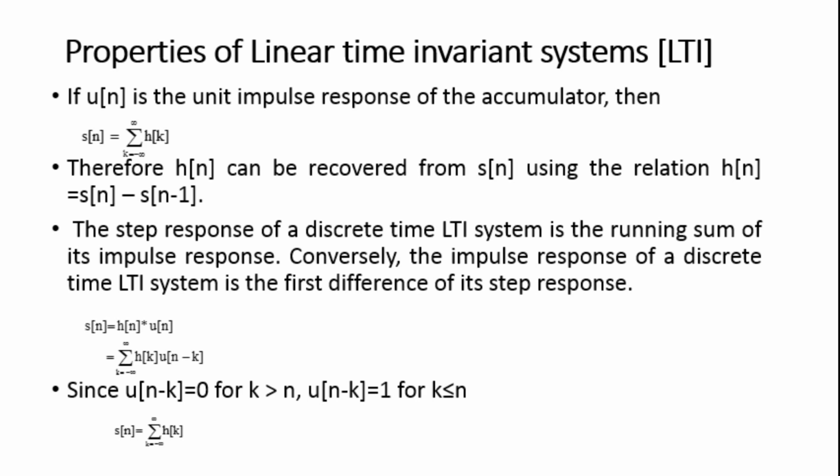The step response of a discrete time LTI system is the running sum of its impulse response. Conversely, the impulse response of a discrete time LTI system is the first difference of its step response.